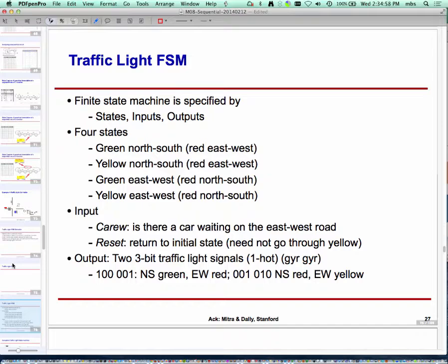So the current state of the system, since there are 3 lights in each direction, you could say I would have 9 possible current states of the system, right? I mean, east-west could be one of 3, and north-south could be one of 3. So 3 times 3, there are 9 possible combinations. But not all combinations make sense in our particular case. For example, we already know that the system should never be green-green. It should never be green-yellow. It should never be yellow-green. It should never be yellow-yellow, right? So 4 states are immediately ruled out of 9, right? So we are left with 5.